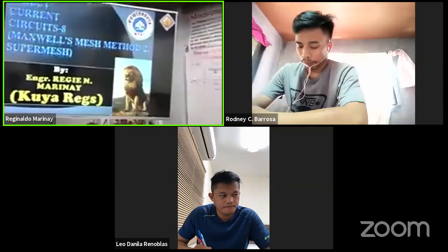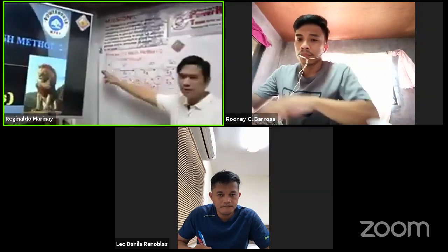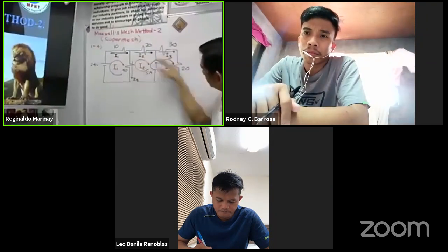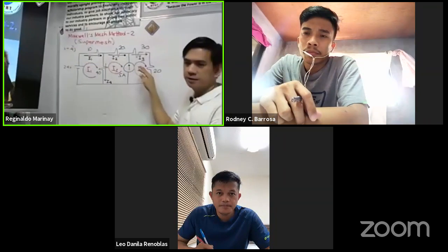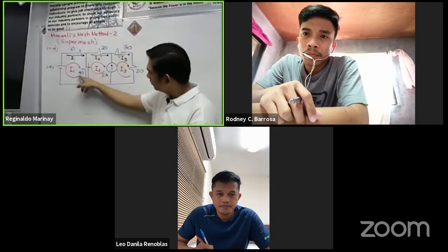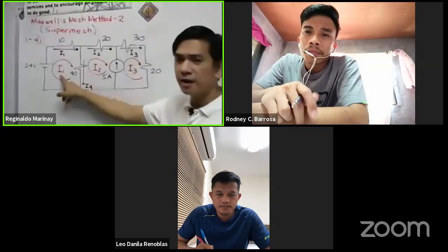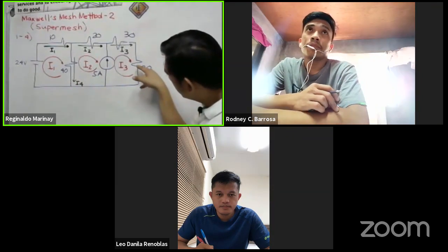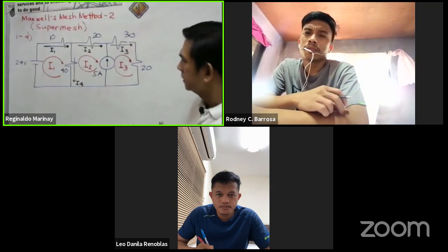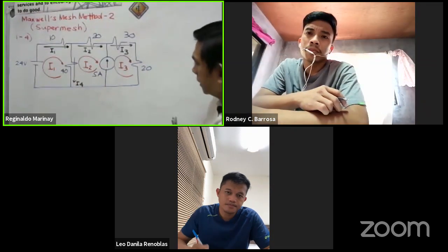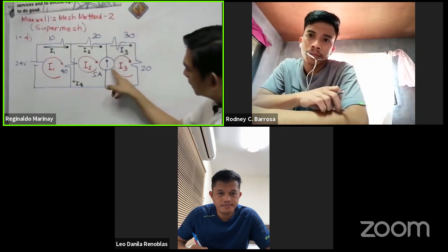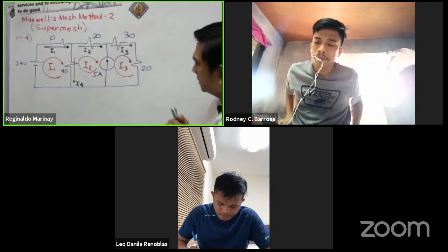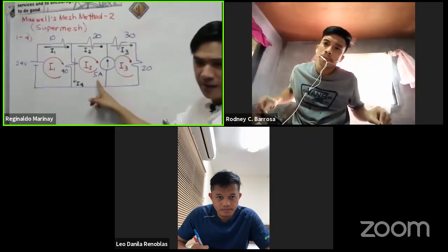We have the Maxwell's mesh method. We have problems numbers 1 to 4. We have a given 3-loop circuit here. For loop 1, I assign the circulating current I sub 1. Loop 2, circulating current I sub 2. Loop 3, circulating current I sub 3. Take a look here. We have a 5 ampere current source. Let us first find the equation for this 5 ampere.